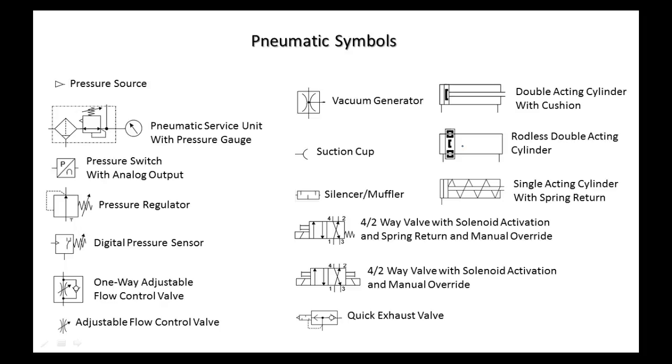The ones we have use magnetics. The piston is just a big, very strong magnet, and whatever we want to move is out on the outside, attached to it magnetically. All the rodless cylinders that we have on both lines work on that concept.